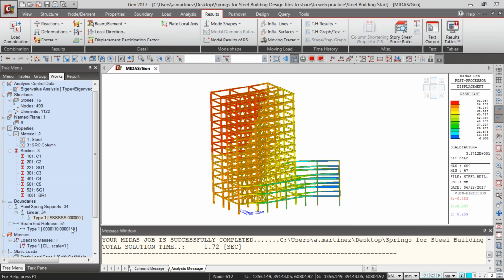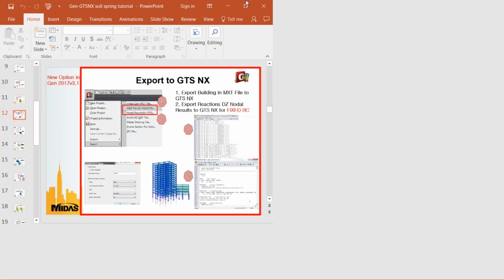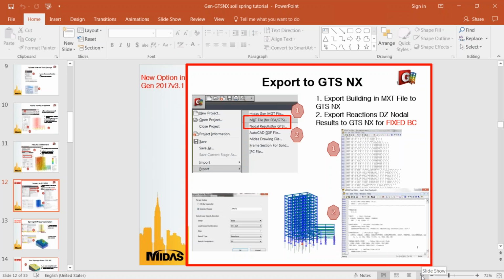But as we saw in the training, we're just giving it a uniform value for the stiffness, which is not ideal. If you got the value from a table, and it's a very soft sand or clay, there are some simplification approximations that you could apply uniformly in some cases that might be more accurate than just fixing the base if it's a soft soil. But it's still not ideal. So the program does allow you to have this interaction. I'll quickly come back to the slides.